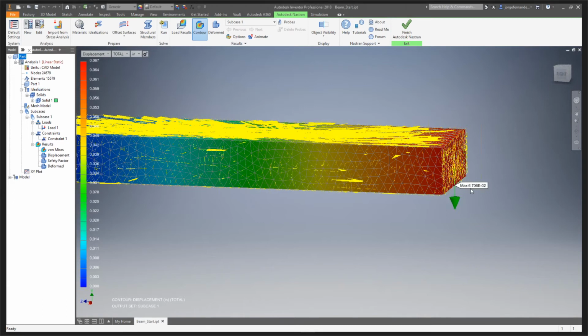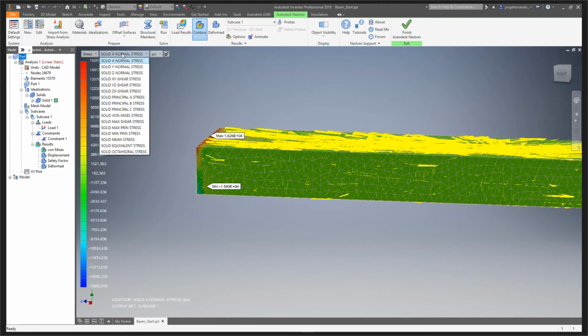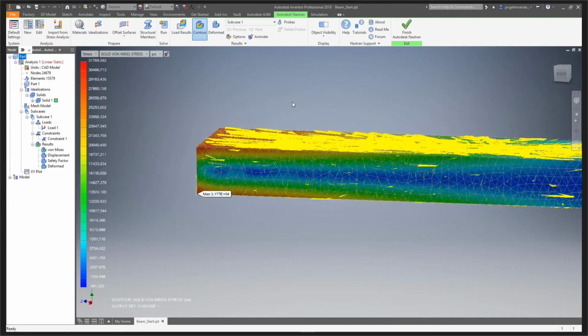Obviously, you can do this to a fault. If you put like infinitely many meshes in there, it'll take longer to compute, right? So that's just the kind of trade-off that you have in regards to simulations. Like, hey, I want my mesh to be fine enough so I get a consistent answer with what I'm expecting, but I don't want it to be too fine that I'm blowing up my computer every time I run the simulation. Yeah, a lot of times you just want to get really close, right, and start getting a feel for what's happening here.